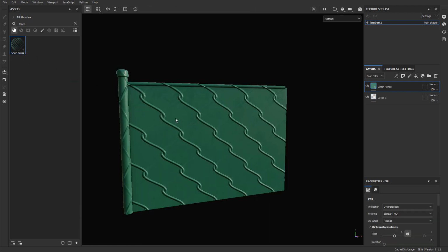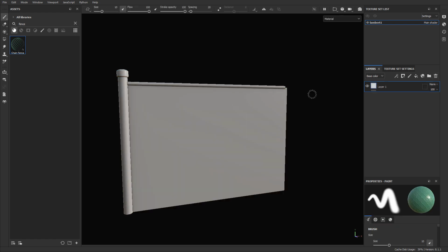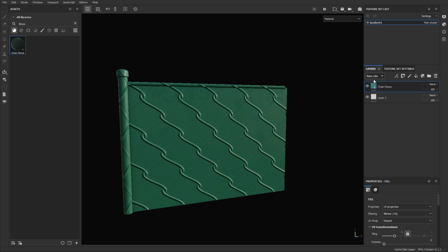However, it's going to apply to the entire mesh and we don't get the opacity for it. So we're going to need to do two things. One, enable the opacity channel to be available in this project, as well as we're going to need to apply just to the flat plane and not to the metal bars. So let me go ahead and delete this. Actually, I can go ahead and keep it just so I know it works. And then we'll delete it from the layers and reapply it again.